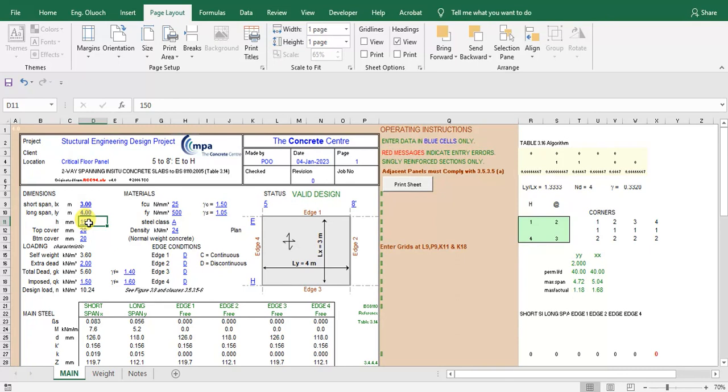Also, you can come to Excel after you've done some kind of preliminary design, and so you know roughly what depth you want, and also the usage of the structure. Because if we have vehicles parking on this slab, then we'll have a thicker slab. In that case, let us just go with 150 for this case.